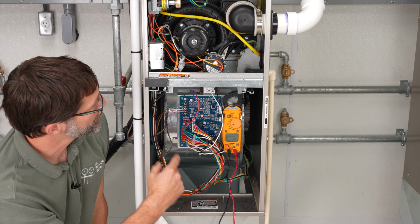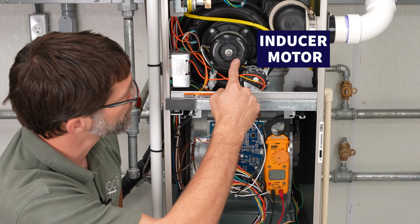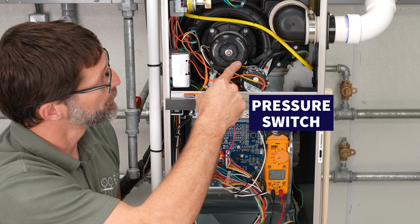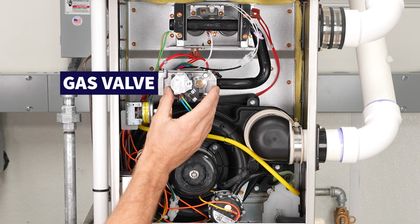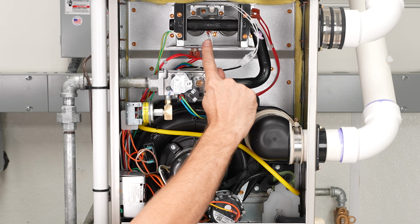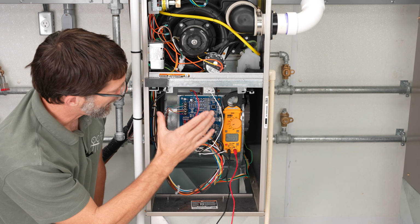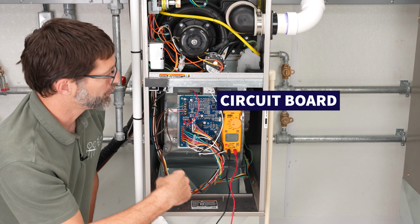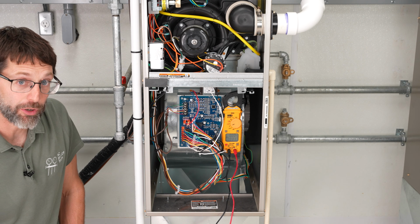The first thing that would turn on after the blower motor ran for 90 seconds is the inducer motor, the pressure switch would prove that this is running, the hot surface igniter would turn cherry red, the gas valve would open allowing the gas to flow through, and then we would have the flame rod proving the flame rectification process. Then after the heat exchanger warms up for about 45 seconds, the circuit board is going to turn the fan on, and that would be how this furnace operates. Now let's move on to the next one.